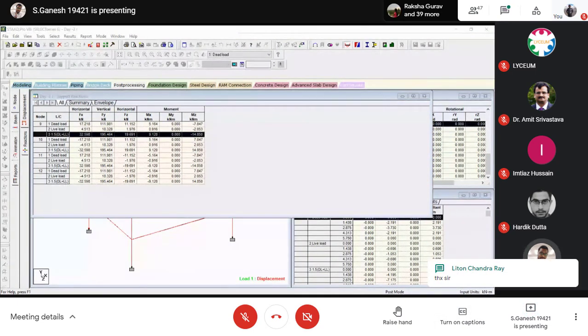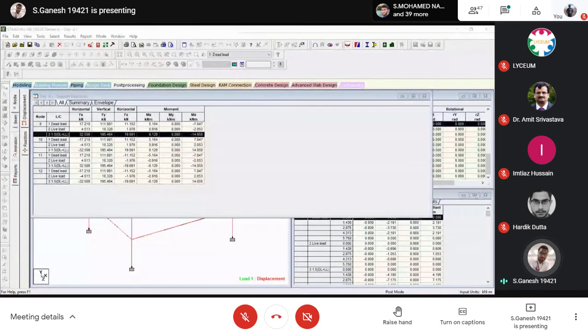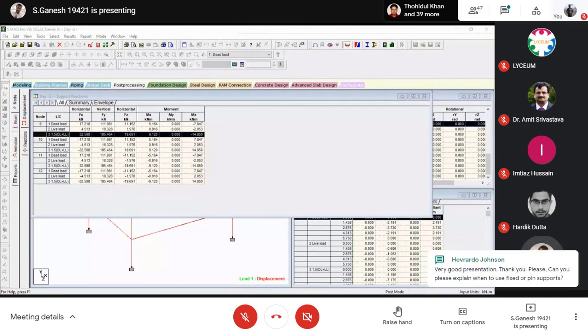Okay, Sahil, we will take care of your notes. Plinth beam in the model, yes, it's required. The ground level is your plinth beam. Whatever software you use, the ground level where your axis coordinate is 0, 0, 0 is considered as a plinth beam, unless you have some basement structures. If you have a basement building, then beam considerations below that certain level will be there. That is called basement beams. Until your ground level is maintained at 0, that is called plinth beams.